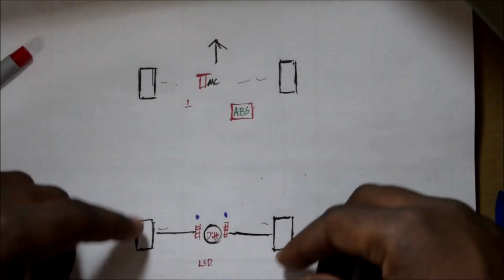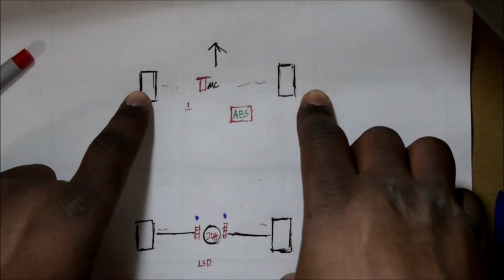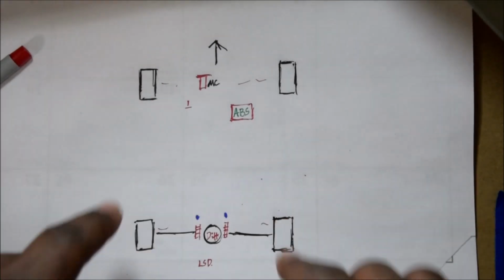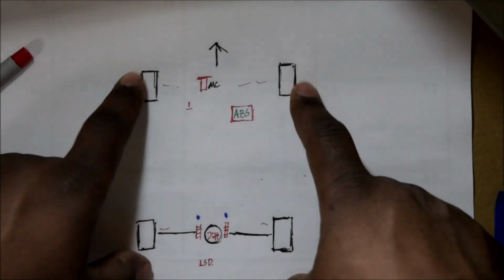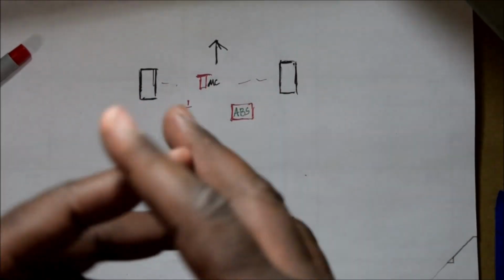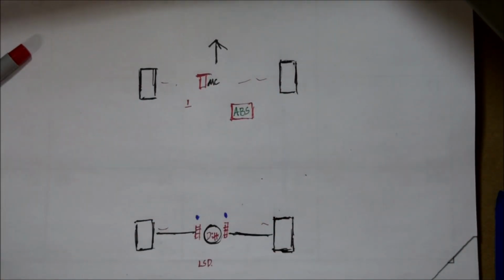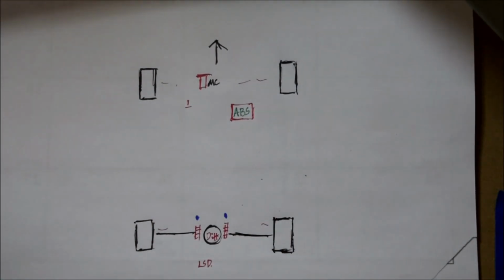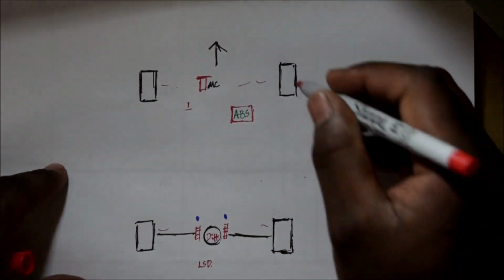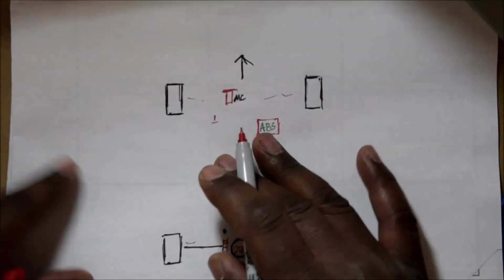If both of them are spinning faster than the front, well, the car says, we got a problem here. Something's going on because we're just wasting power in the back and the car is not really moving. So what comes in is torque management. The torque management of the TCS system basically cuts power. Okay? So let's note that somewhere.